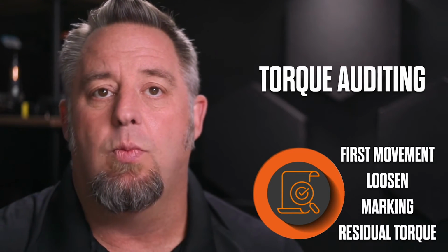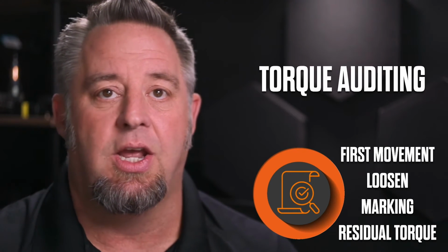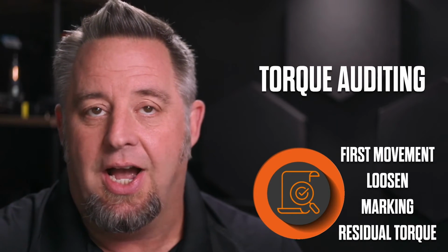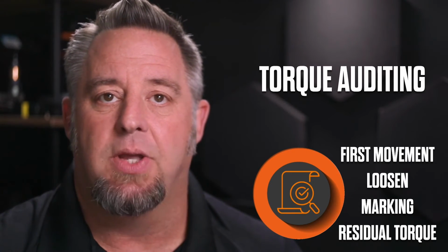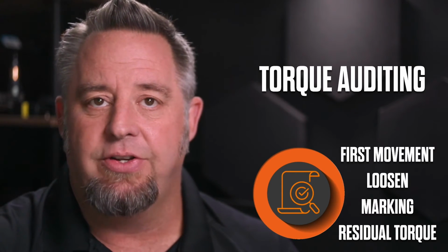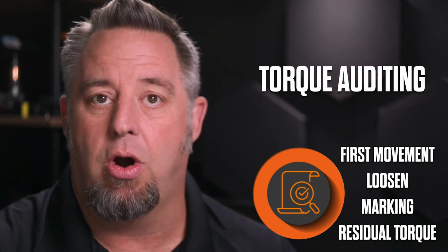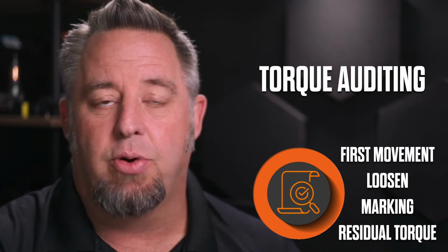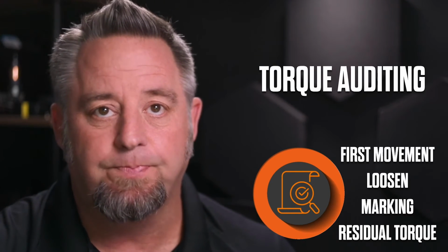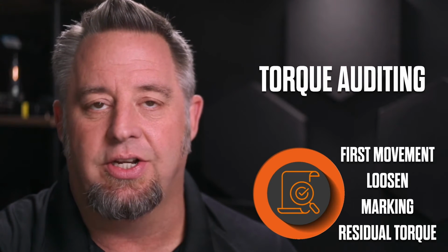And so by doing a number of different tests within whatever torque auditing process you might want to do, at that point you would be developing a little bit of an uncertainty process of the values that you see when you do the auditing compared to the values that are during the actual process. And so you can develop a correlation between those two to verify if you are getting the correct torque value.